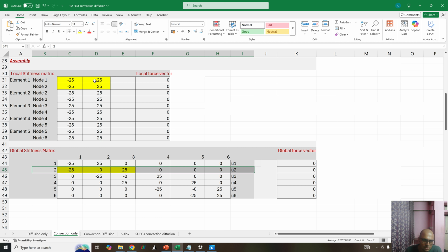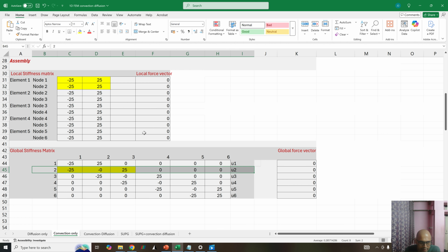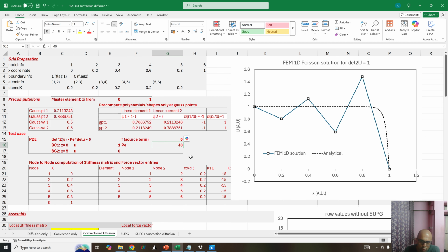Okay, so this is a bit different, and when you try to take the global stiffness matrix for that, you are getting this kind of a case. What you're getting is basically almost zero terms at the diagonals. If I try to highlight this equation for node 2, u2 is getting multiplied by almost 0, which means that this equation is not really representative of u2's identity. It is actually representative of u1 and u3's identity, and somehow the solution is trying to derive u2's value from the other two nodes.